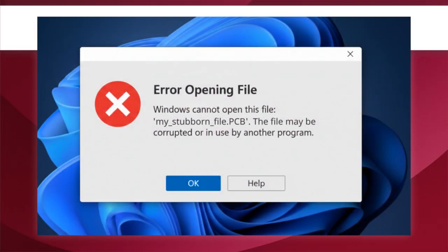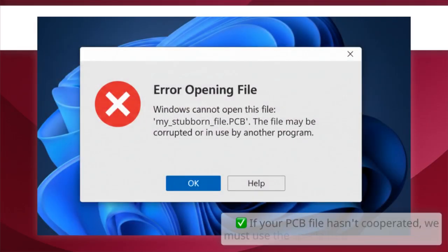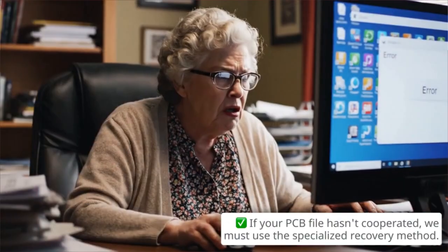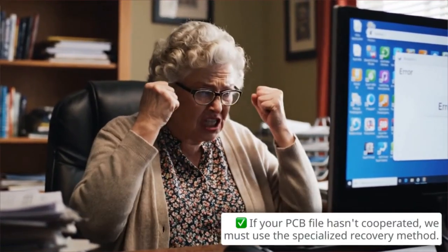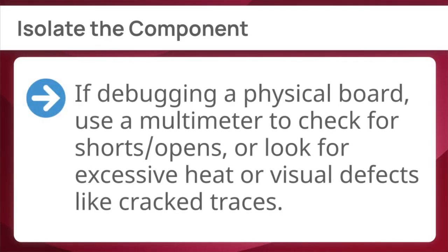If your PCB file isn't cooperating, don't worry. It simply means we can't rely on the initial software anymore. I need you to take these 3 direct actions to effectively isolate the file error. First, isolate the component. If debugging a physical board, use a multimeter to check for shorts or opens, or look for excessive heat or visual defects like cracked traces.